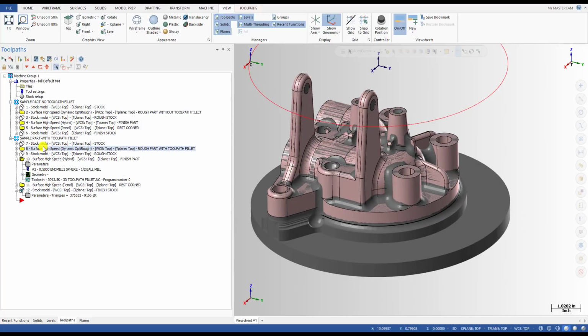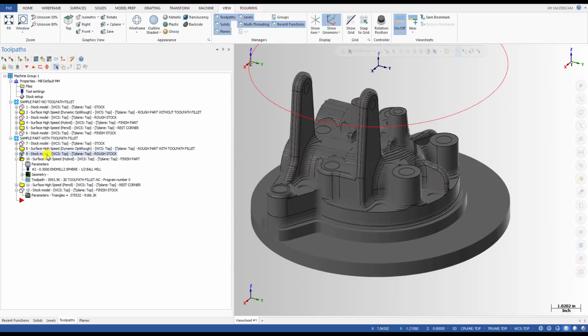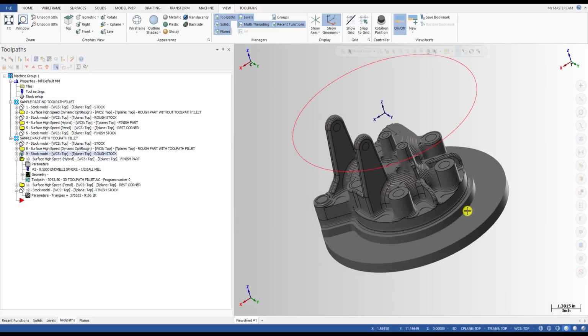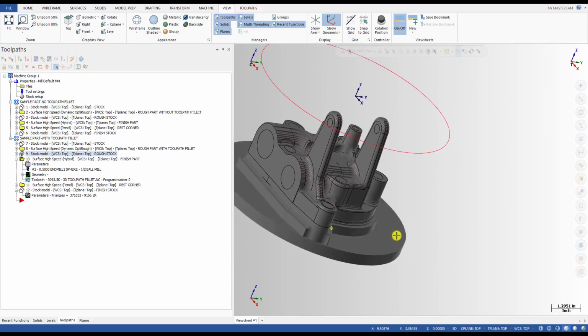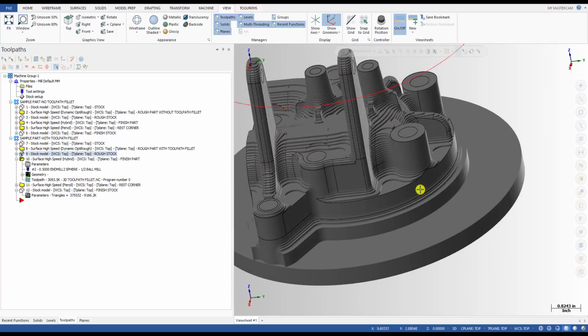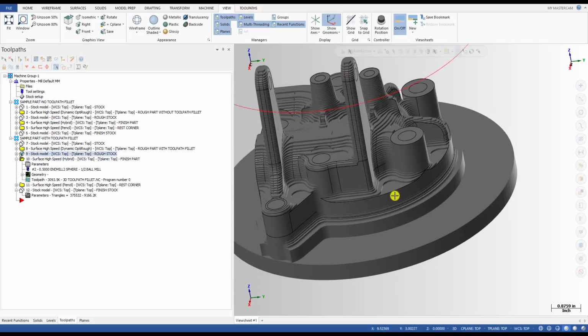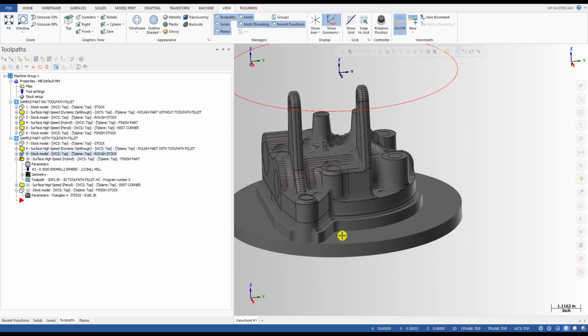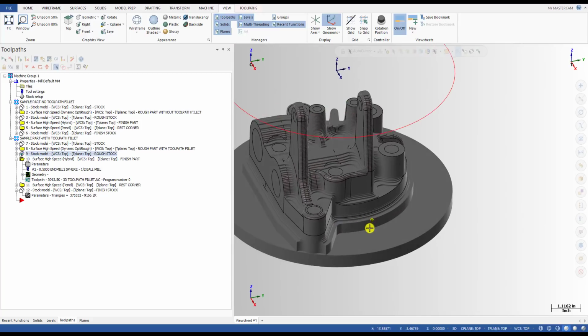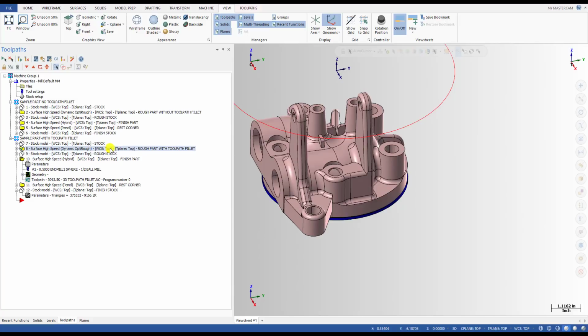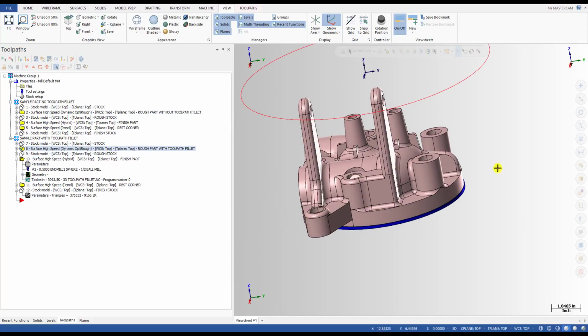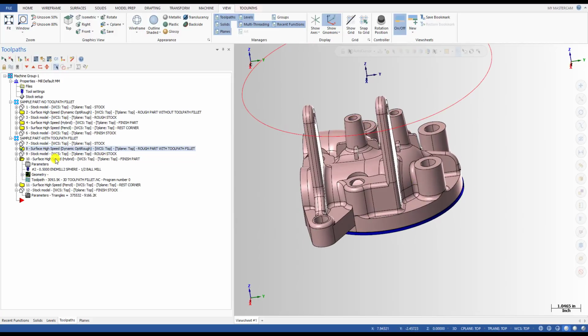So when you activate the Toolpath fillets, just make sure you don't leave any uncut material here, because with this option activated, you leave more material here in the corner, but you also make a fillet here at the bottom of the part, and so that's why we have some uncut material here, and that's not good for the finish tool. So if you use this one with Toolpath fillet, you need to make another Toolpath for cleaning the bottom of the part before we do the finish cutting.